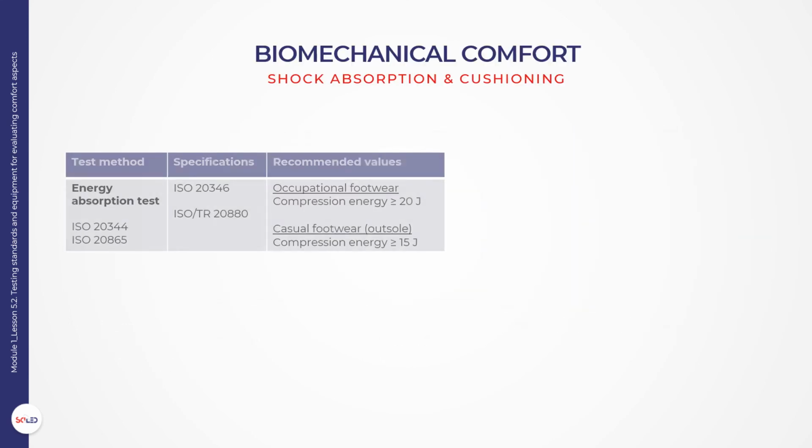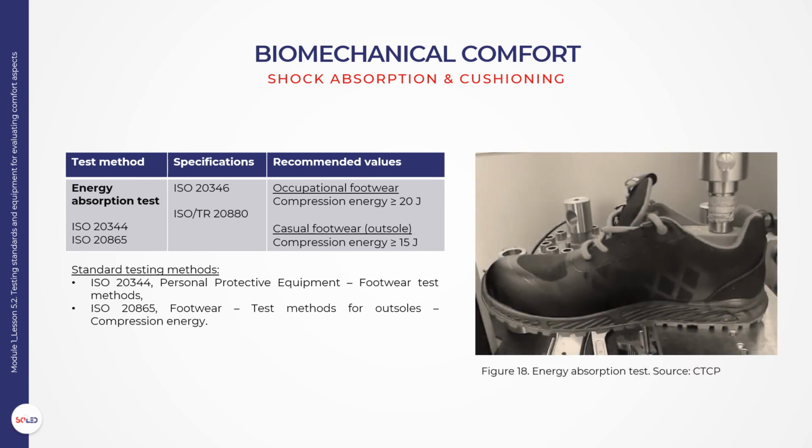Cushioning. Cushioning is associated to the ability of shoe bottom to conform elastically to the shape of the foot and the plantar pressure distribution while walking or standing. Cushioning energy is the energy required to gradually compress a specimen of the material up to a standard pressure as measured. The specifications and requirements for occupational footwear is that the compression energy shall be greater than or equal to 20 joules. In the case of casual footwear, outsole, the compression energy shall be greater than or equal 15 joules.